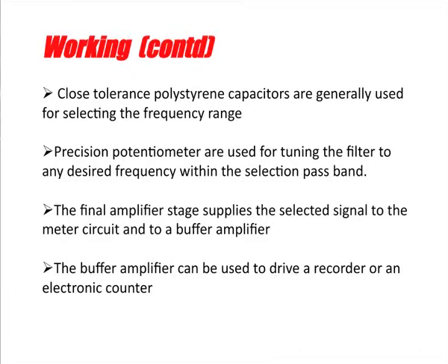Now, the most important thing is about the capacitors and the resistances that have been used in this filter circuit. We generally use close tolerance polystyrene capacitors, since they show very high accuracy, and simultaneously high precision potentiometers are used for tuning the filter to any desired frequency within the selected pass band.